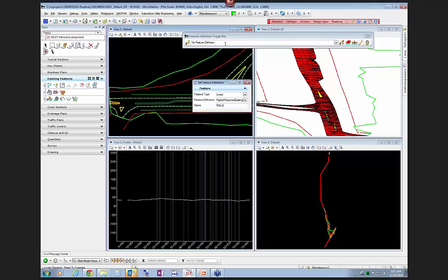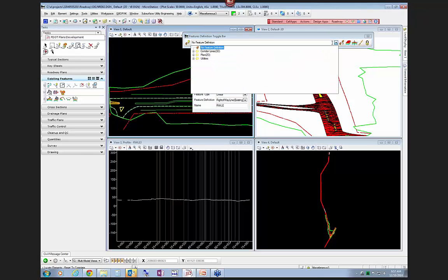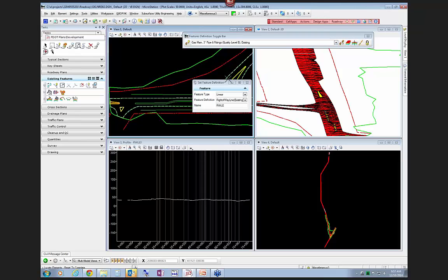And if you want to set a feature and make it active, you can go to this utilities menu, and I'll pick gas. I'll just pick a 3-inch utility line. And then if I click this button here, that makes it the active feature that I draw. So anytime I go to use a drawing tool or use a set tool, it will essentially use whatever's in this dialog.